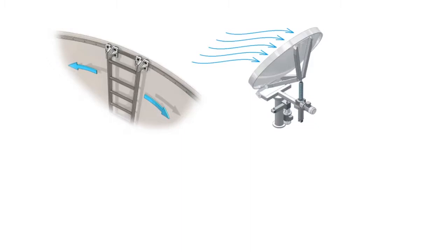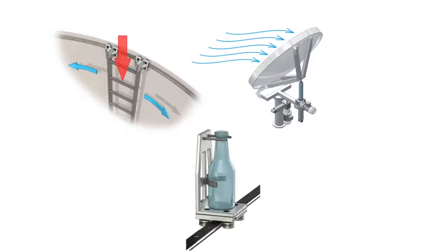Any structure can be subjected to static and dynamic loads. When we look at an application, we are interested in the loads seen as the system is moving, the dynamic loads. We do not, in general, consider the loads seen when the system is stationary. However, in cases where loads are high, we do check these are within the capacity of the unit being specified.